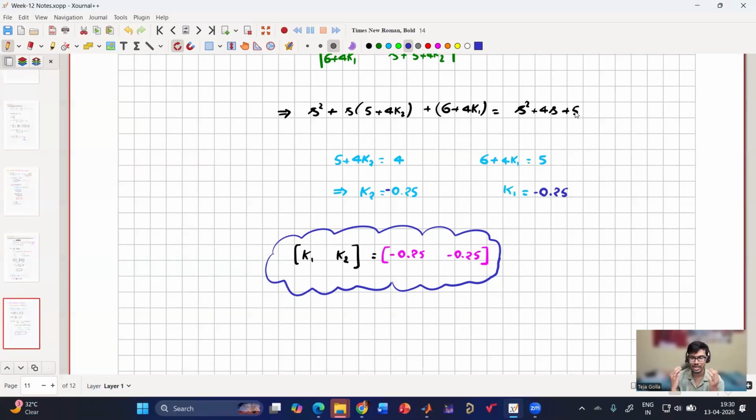So in this way, we can correlate which is varying what. And we will also get the intuition that by varying this, these things are getting varied, or if we want to vary this, we have to change this. So in this way, we can see how the poles are moved. We have 2 degrees of freedom, right? Here we have K1 and K2, and based on K1 and K2, we can move like this or like this. But because they're complex conjugates, there will be a mirror image with respect to the x-axis. In this way, we'll be solving and we'll get the K1 and K2 unknowns, and we can also correlate how they're related.